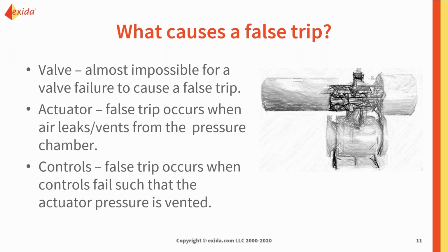So first, let's think of a valve. It's your simple butterfly or simple ball valve, and it's just that simple mechanical device. There's nothing smart about it. There's no actuator, there's no solenoid, just your valve. It can't really decide to act on its own. It really doesn't have that many safe failures or spurious trips that could happen if you're talking about just the valve. It's pretty hard to find false trips there.